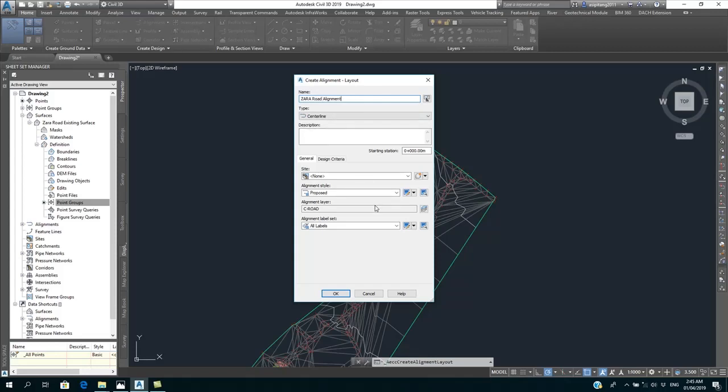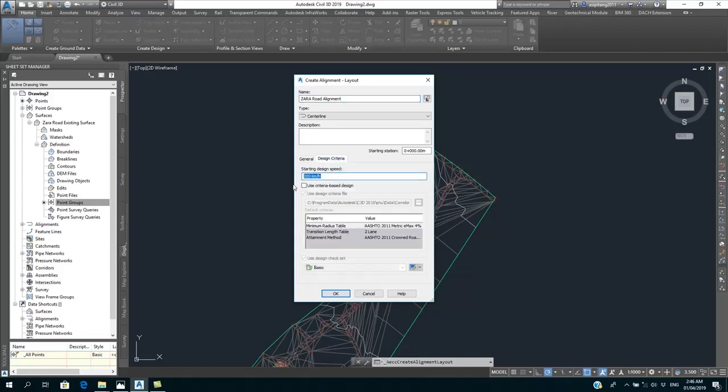For instance, in Nigeria, we make use of the Federal Highway Design Manual, Volume 1 on geometric design. The parameter stated is what we're going to utilize on this project. And for this project, this 1 kilometer distance road is a street road, and the design speed is between 40 to 60 kilometers. If you have that reference, you can always check the Federal Highway Design Manual as reviewed in 2013 as stated. But in case we are using the design speed of 60 kilometers for this kind of design, so I'll set the parameter to 60 kilometers.